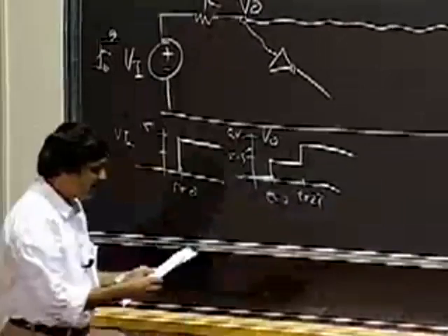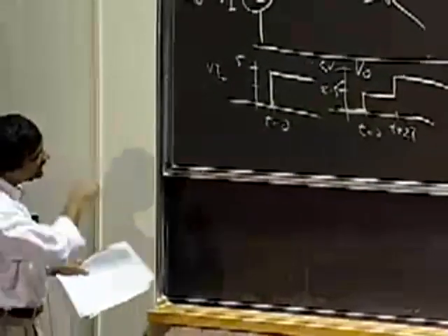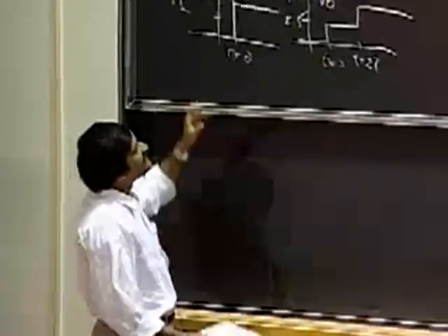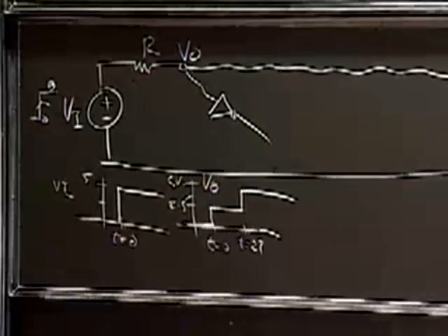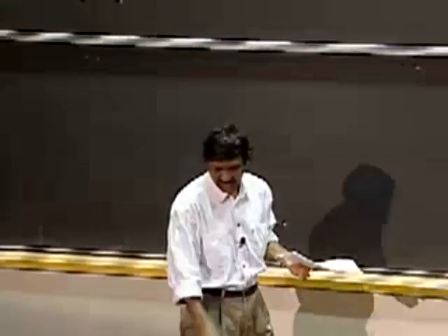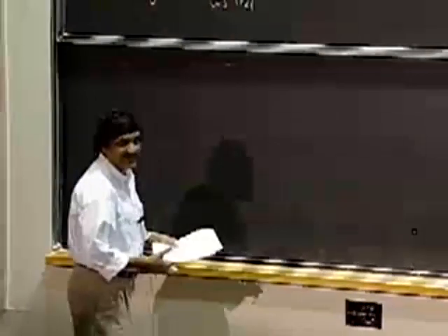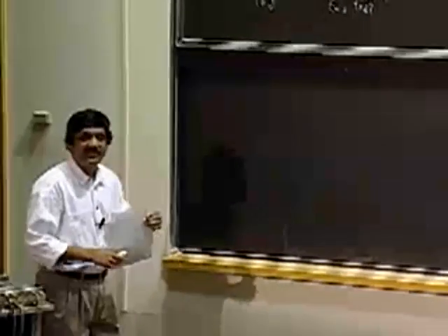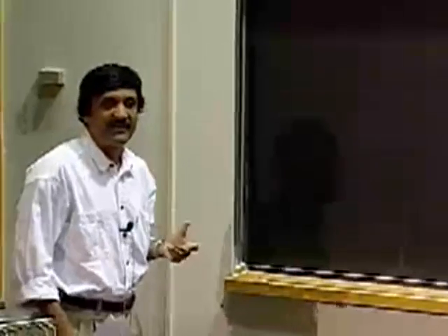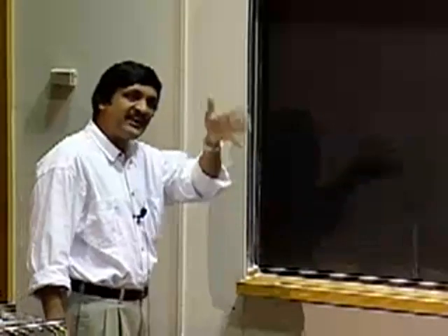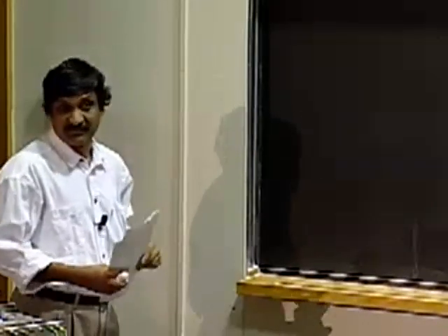So the way to view what's going on is that I have this long wire. In the very first lecture, I started off by saying wires are ideal. Ideal wires are such that I can transmit signals on them. Wires are small so that the propagation time of signals is inconsequential compared to the rise times and fall times of the signals of interest.